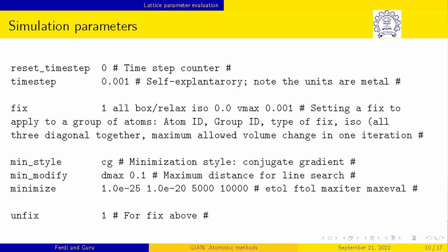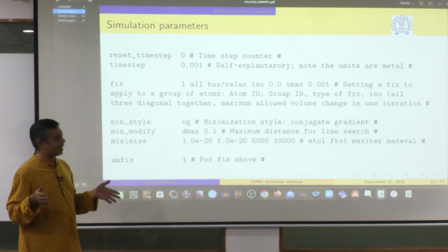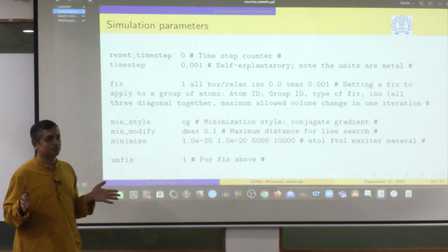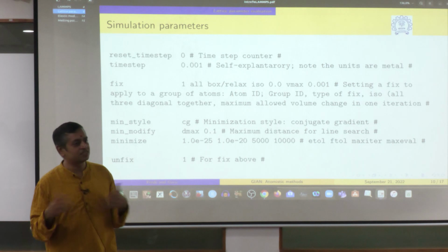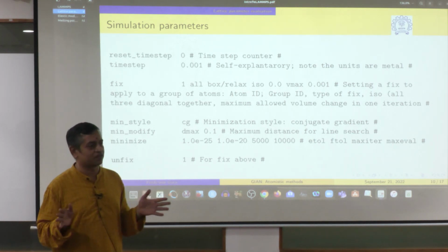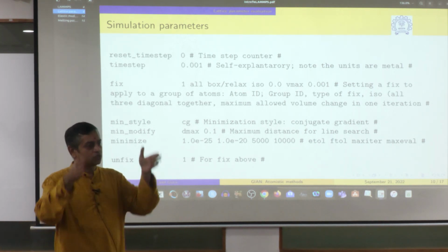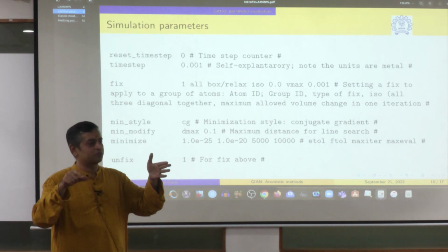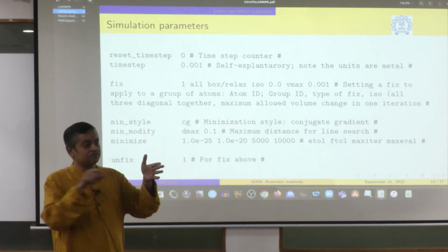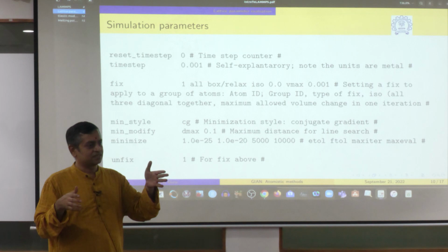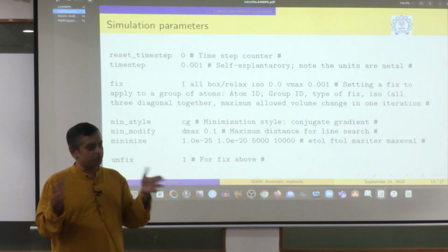I did not mention temperature, but if I give a temperature and I do want to know the lattice parameter, I can't use minimize to get it, because it will quench: the velocities are 0, which is equivalent to 0 Kelvin. So in that case, I have to equilibrate the box at that temperature, then take the Lx, Ly, Lz. In all steps they will not be equal.